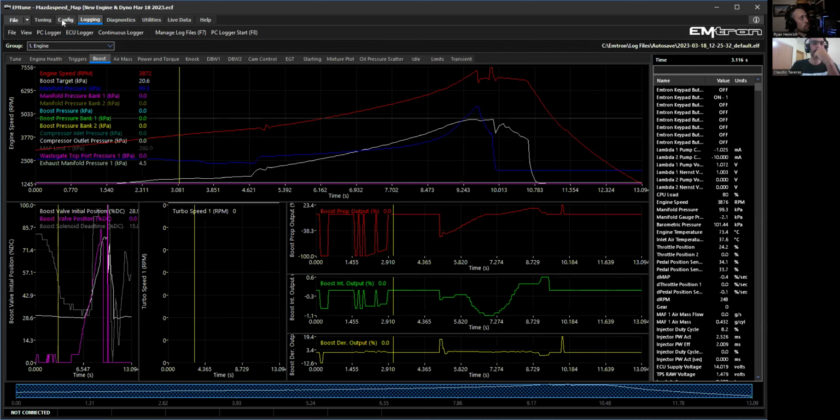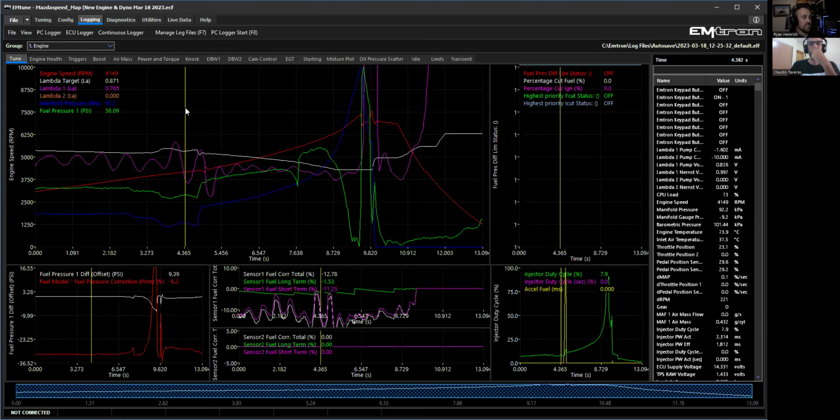One thing that's really good with this, and I was going to show, is that Fuel Tech does something kind of similar, but a simplified version. As you're going through it, you click, is it Q? One of the buttons will go back to the original. Let's say you're doing fuel or boost control on your tune file, and it will have a quick back and forth between your logging and your tune file. Let's say we're looking at our boost duty, it can quickly go back and forth between them.